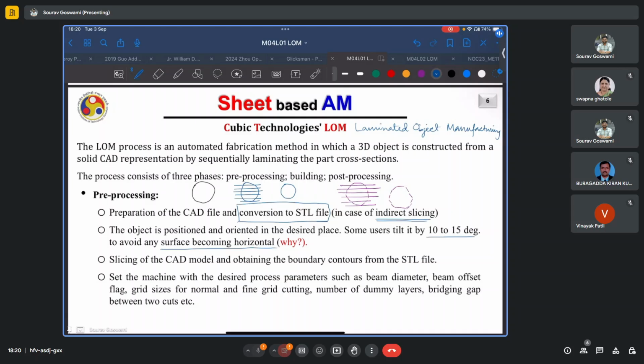Now, these support materials will extend from this horizontal surface onto the build plate, or in some cases, from this horizontal surface onto the part that is being built. Later removal of these support structures often leaves remnants on the final build surface. And it might not always be possible to get rid of these remnants. Thus, the surface quality of the part is affected. That is why typically we would want to avoid, or minimize, the number of surfaces that are horizontal in any build.